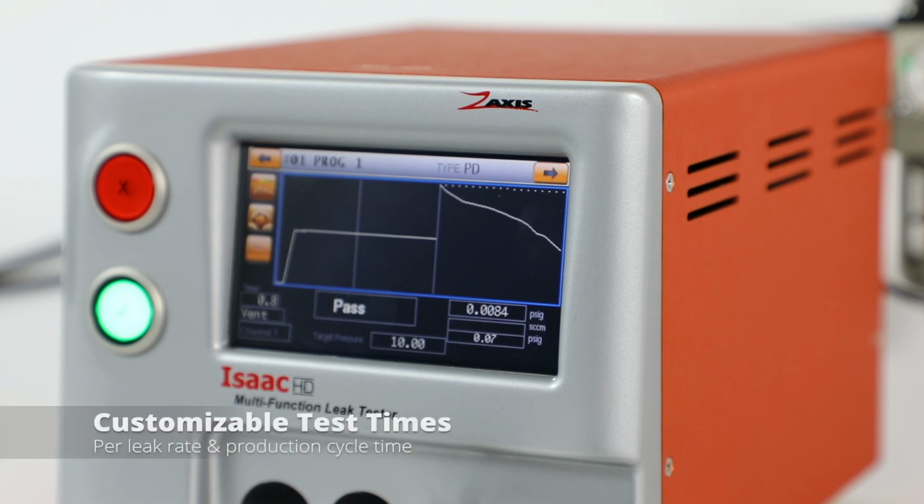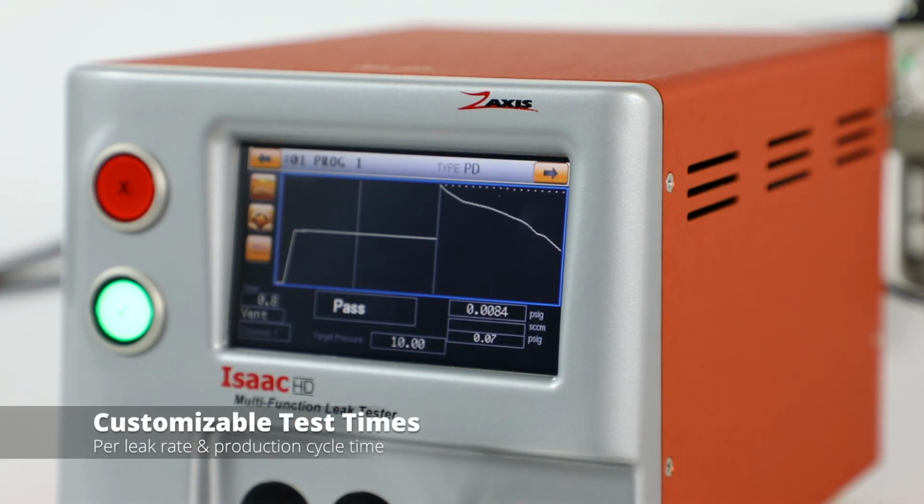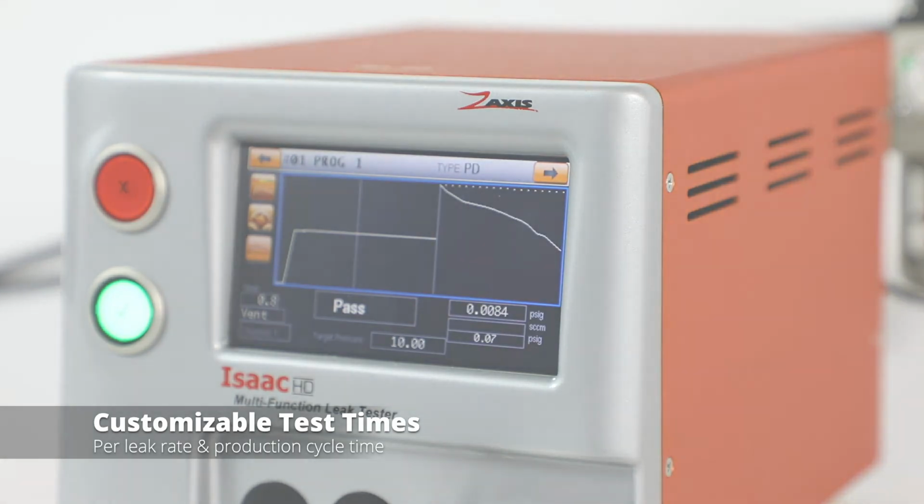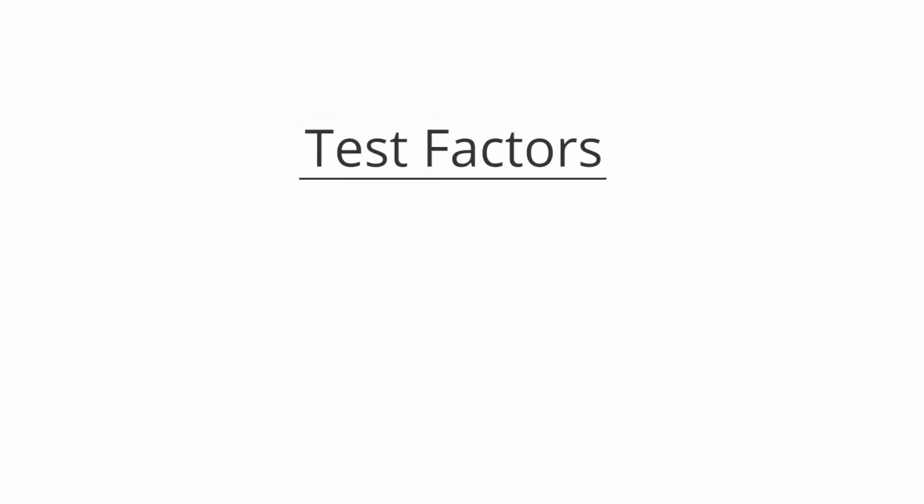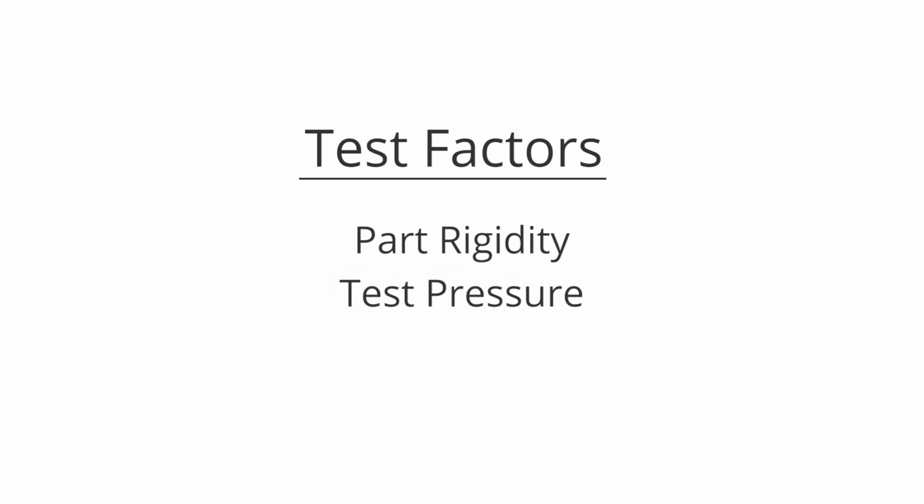So what you're going to find is there are many variations of test times. It really depends on the leak rate you're looking for, the cycle time your production rate has been asked you to achieve, and then balancing the factors such as, is my part a soft part, hard part? What is the test pressure? High? Is it low? But in this way, you can develop your test based on your needs.